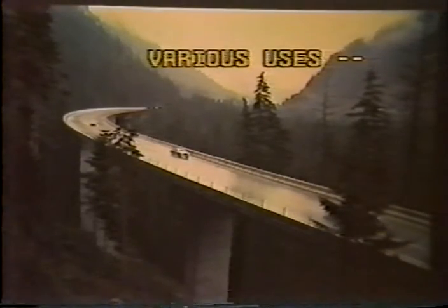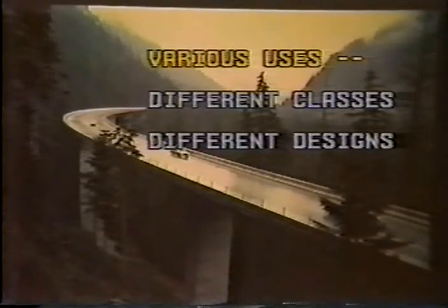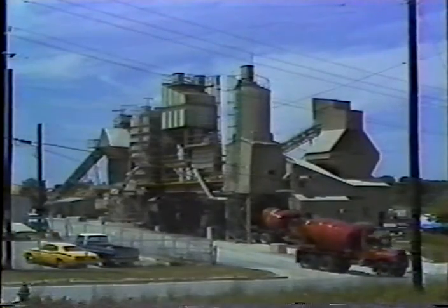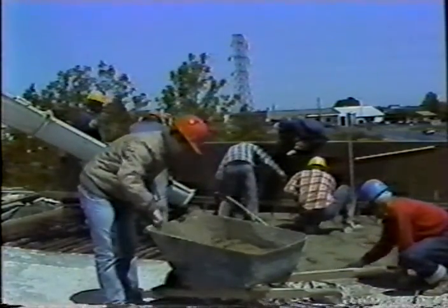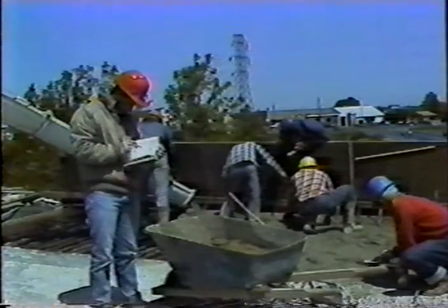Because of the various uses for concrete, there are different classes of the material. Each class of concrete is based on a different design. That's why testing is necessary, to make sure that the mix that was specified by the designer is delivered to the job site, and to make sure that the concrete is mixed consistently. A problem at the plant will show up in the field test results. That is why the inspector's on the job, to make sure the department gets the quality it pays for.